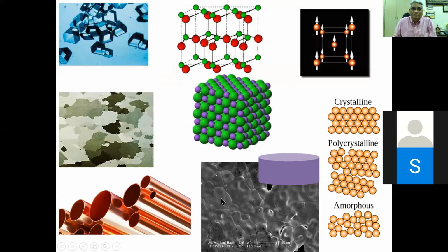Imagine this one is inside one of the grains, and the same structure is in the other grain, and the grain boundary that separates these two blocks is causing the trouble, because between two such blocks, the grain boundary, the defect, causes the termination of the atomic arrangement, right? So you may have loosely bound atoms there, and loosely bound atoms sitting at the grain boundaries are more reactive, they have more energy, than atoms that are bound into the solid. Because I can't take this as an individual atom and talk about its reactivity. No, because it is already formed into a solid, and so it has a cohesive energy. So to make it act as a single atom, first I need to break it out of this bonding. Then only I can make it react as a single atom.